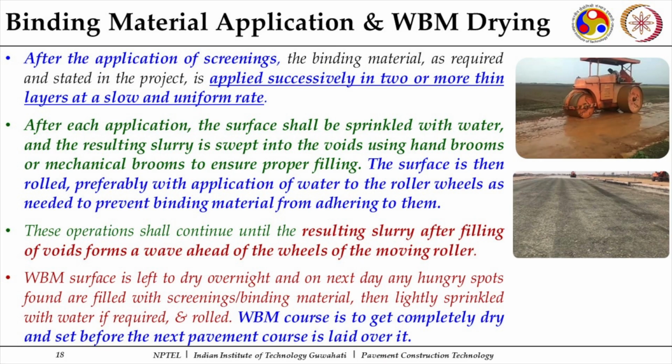But the important aspect is that waterborne macadam is to get completely dry and set before the next pavement course is laid over it. This is an important exercise. If this is not ensured, the water remains trapped inside that layer, and if it is used as a base course followed by a bituminous course, it will damage the upcoming layers. So, it is very important to ensure that whatever water is there, that layer becomes dry, and then you proceed with the construction of the next layer.